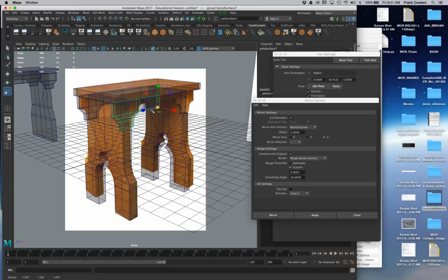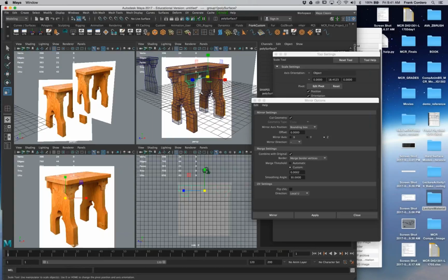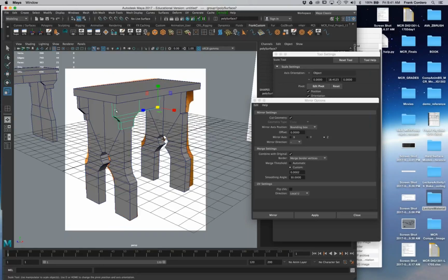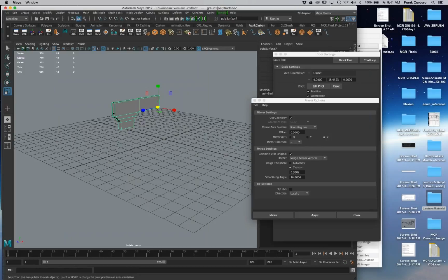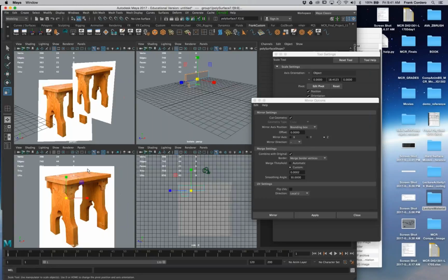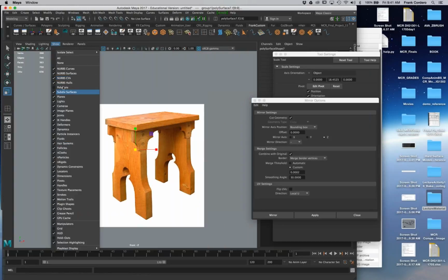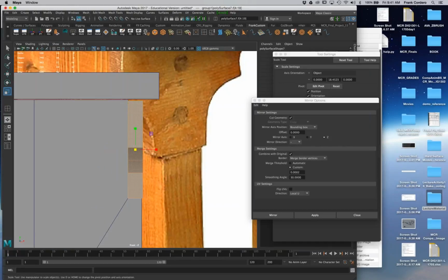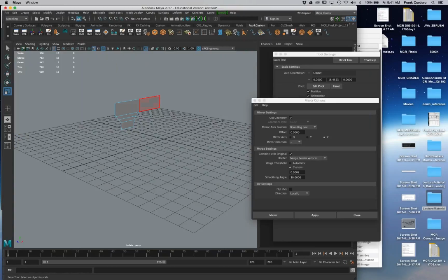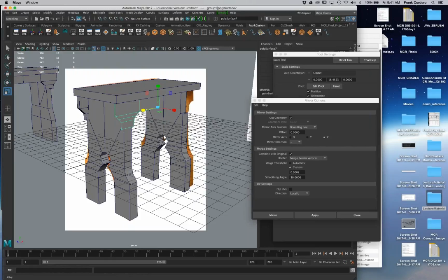And again, let's see. I think I'm going to need something up here. So you know what? We're going to go flat again. So this is the part where I'm like, all right, I'm going to go flat. Every once in a while, I make my life a little bit complicated. Well, if it starts to get complicated, let's go make it simple again. So what does that mean? I'm just going to literally go ahead and get rid of those middle faces. Show polygons. I'll just go get rid of this, because it's always easier to edit stuff when it's flat first.